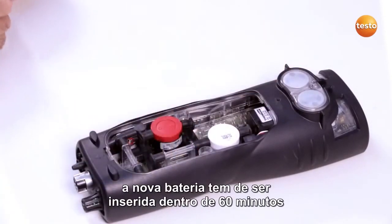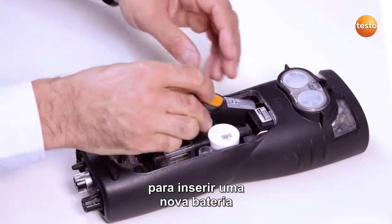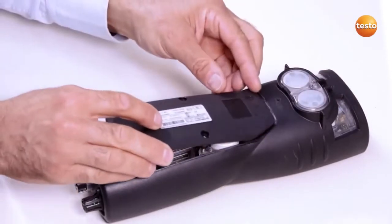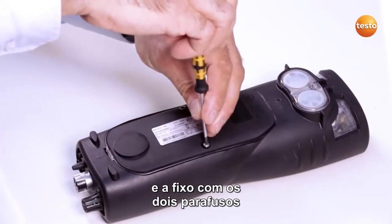The new battery must be inserted within 60 minutes so that no data is lost. To insert a new battery, I slide the battery into the guide rail until it clicks into place. Finally, I replace the service cover and close this with both screws.